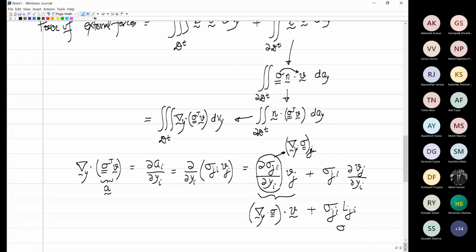And this you can also write as, it's called double contraction. So I think you have seen this also in my lecture. Sigma double contraction big L. So double contraction is when you multiply component wise and just add it. Single contraction, that's the dot product. A dot B is AI BI. And here we have double contraction because you are contracting over both the indices.